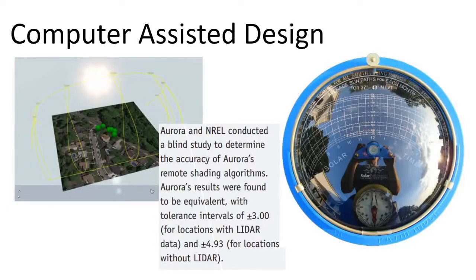So the other drawback of solar design tool is it does not do shade analysis. Trees are tricky, and not being able to model shade because of trees can land you into problems. It used to be we would get up on the rooftop with a survey tool, and it would read a chart and let us know when the sun's going to shine and when it's not. You can literally just carve out, based on where these shadows are, a percentage of your solar production